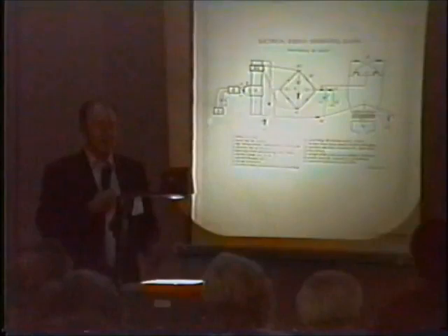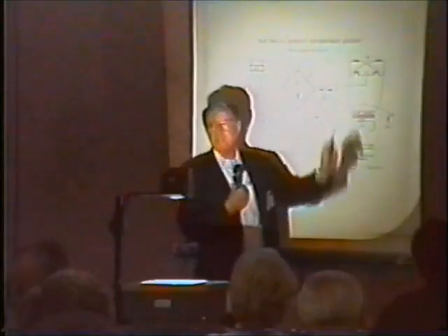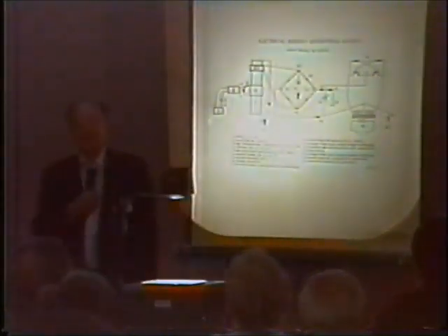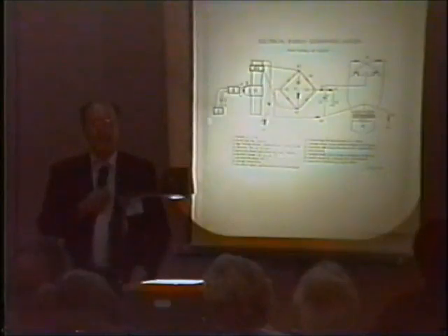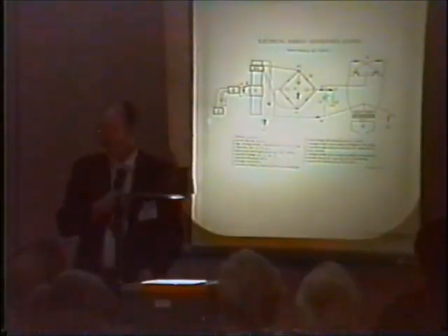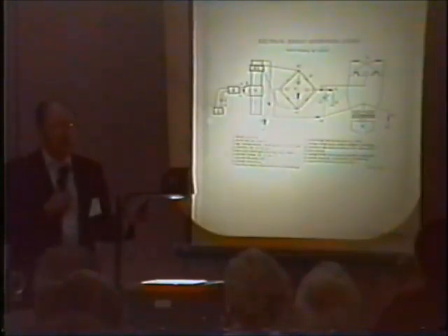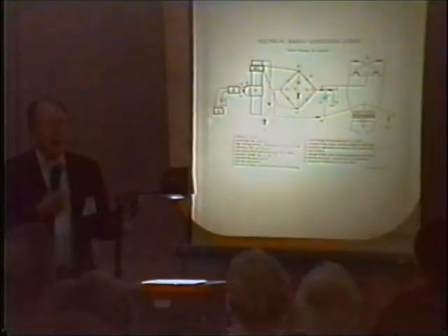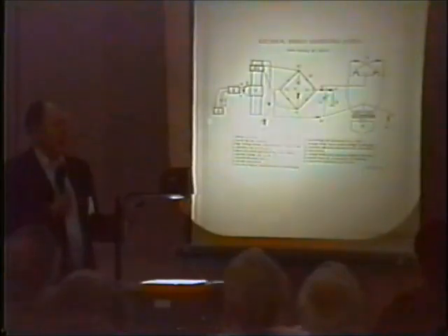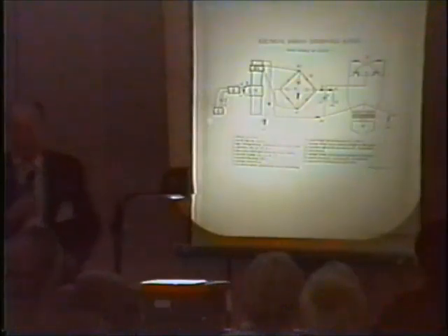And they've got some other characteristics which change it, and these transistors also have capacitance and inductance too. So if you're trying to balance up your impedance on something like this, you can be balancing all day long and a lot longer than that and still not get anything. You've shot yourself out of the water unless you just happen to luck into it, and it gets to be very skillful. Now, the way you get around that is that there are capacitors and inductors and resistors that are actually just that and nothing else.